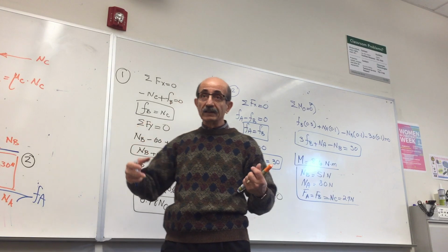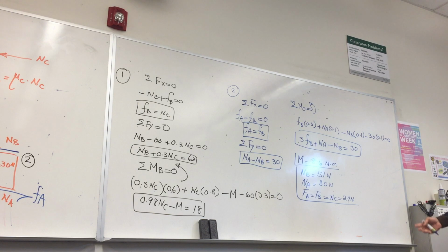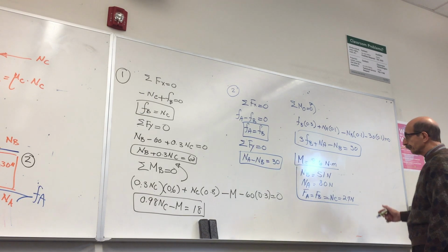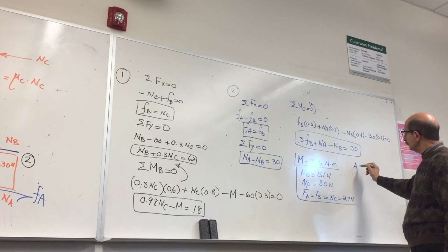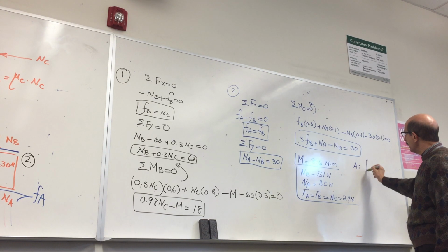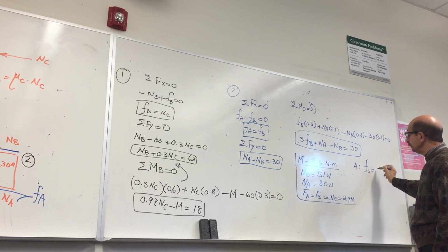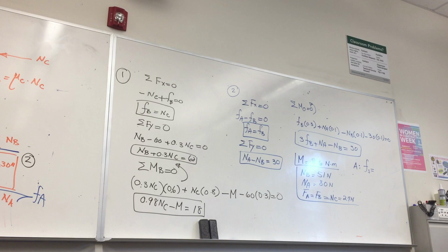If they're less than the maximum friction force that can develop there, obviously there is no motion. But if they're bigger, obviously motion takes place at those points of contact. So we need to find the maximum friction forces at both points. Let's first find at A. At A, the maximum force of friction would be coefficient of friction, given as 0.4, wasn't it?